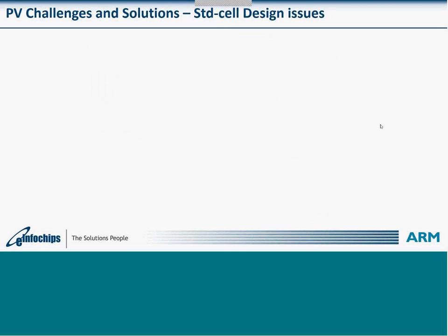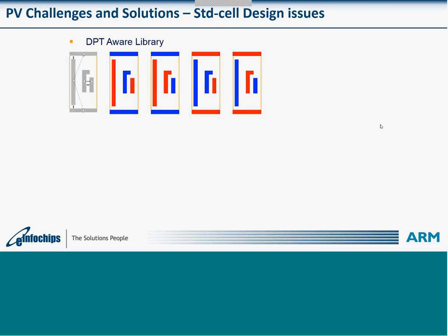Right? There's a related design issue. Standard cells are basically the building blocks of our PNR digital implementation. It has two different aspects. One is standalone standard cell generation, and the other is the full standard cell library. Let us speak about only one standard cell first. For that one standard cell, we have to take care of these double patterning issues within the cell itself.